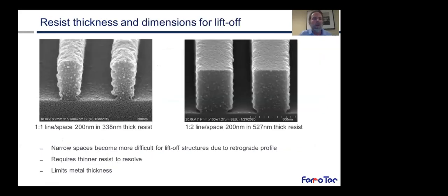So here we show the resist thickness and the dimensions for the liftoff. Now, our tests were run here with 2 different resist thicknesses, 338 nanometer thick and 527 nanometer thick, and we worked with lines of 200 and 300 nanometers.